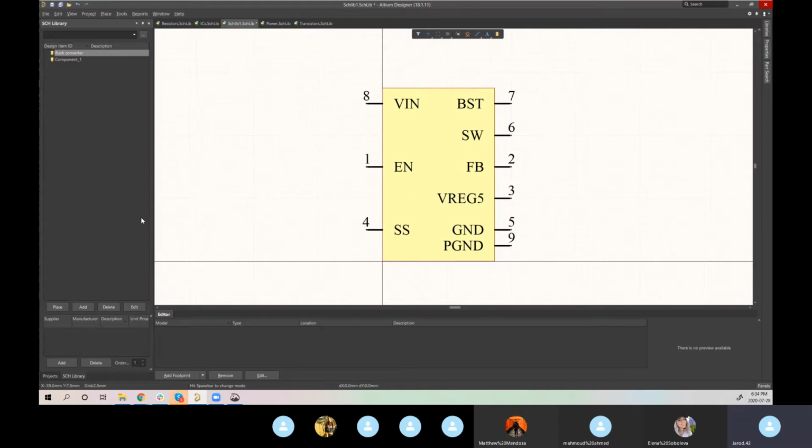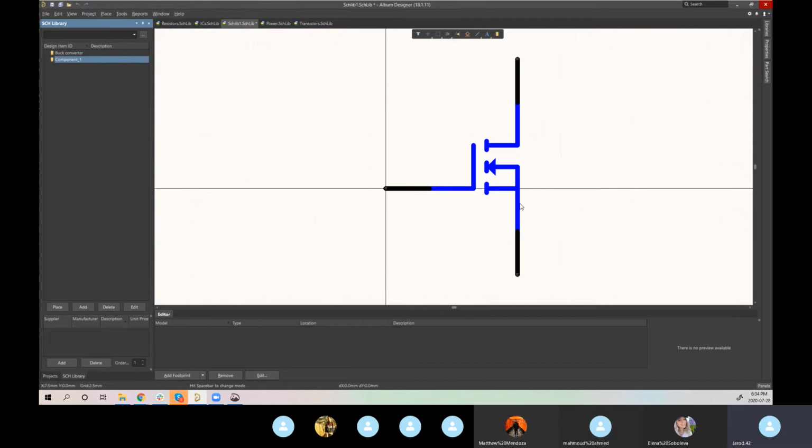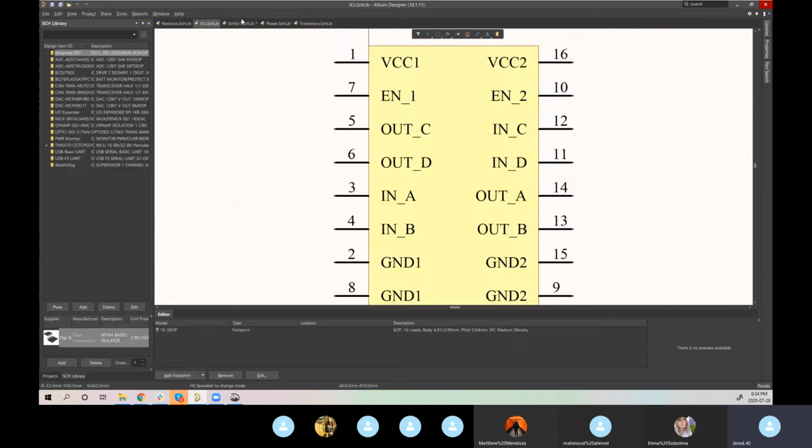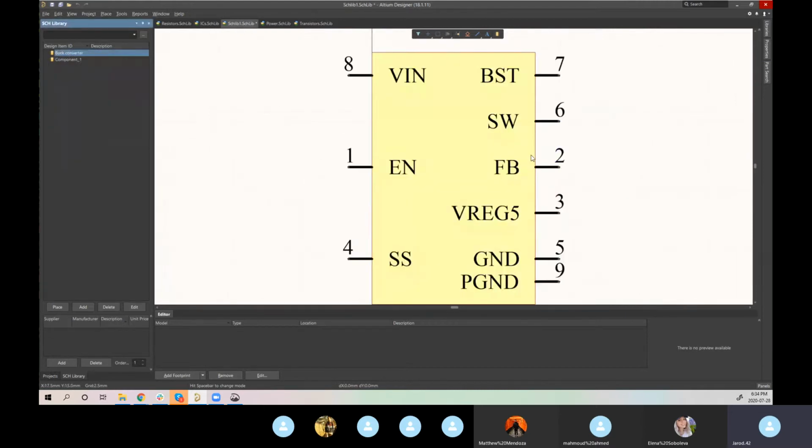Anything else? Jay's typing. Yeah, so whenever you're making components, if they're easy, just diodes, resistors, transistors, something that just has the standard symbol, you can draw it out. Easiest thing is going to an old library, copy paste. And then if it's something like an IC or multi-pin chip, you just place a rectangle and then pins on the outside.